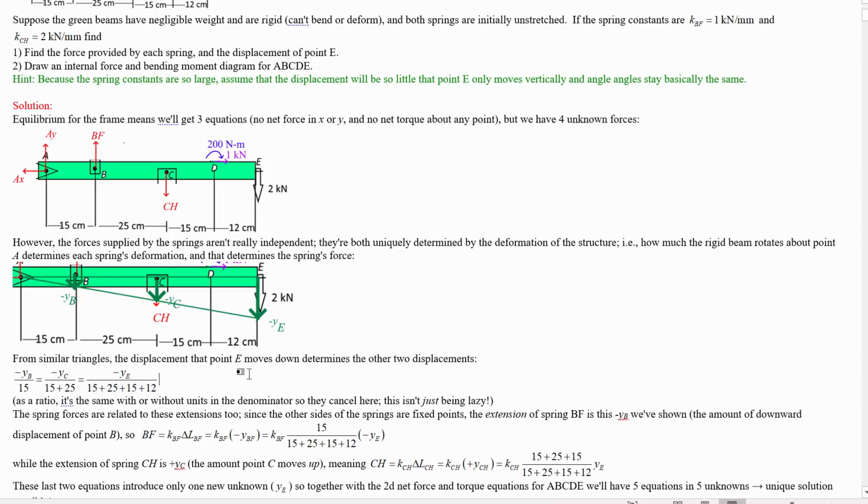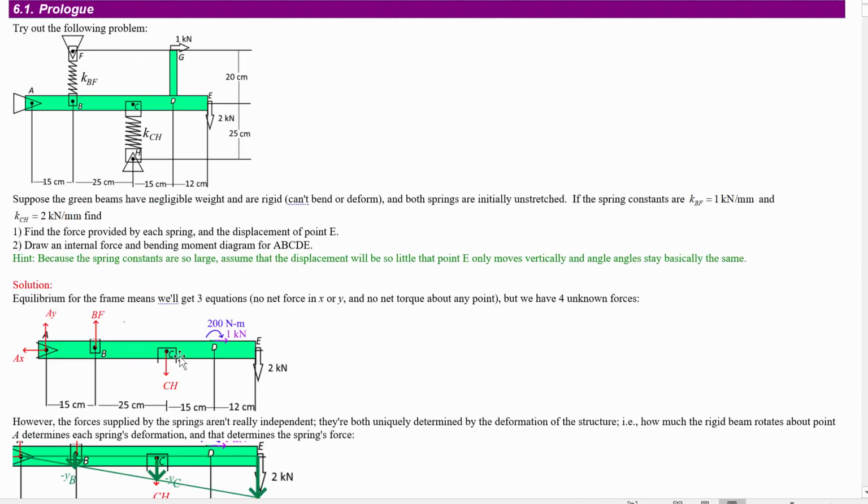Okay, so with that, just stepping back for a moment, we can relate the displacements of this point and this point together to the displacement of this point at the end. Really, those 3 different displacements are not independent. If we know what the angle of bend is, the tiny little amount that this is going to bend, then we can figure out the vertical displacements of each of these points. There's like one variable, 1 degree of freedom there, how much they bend.